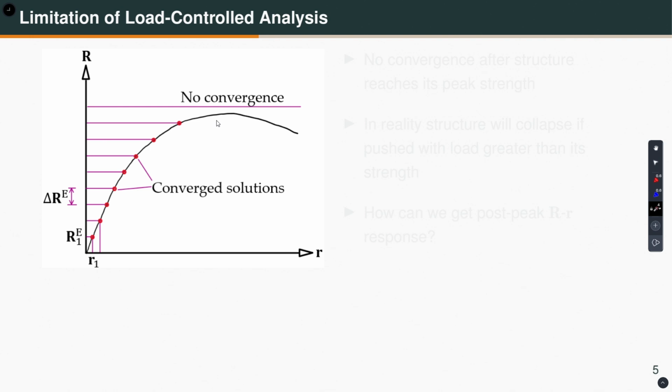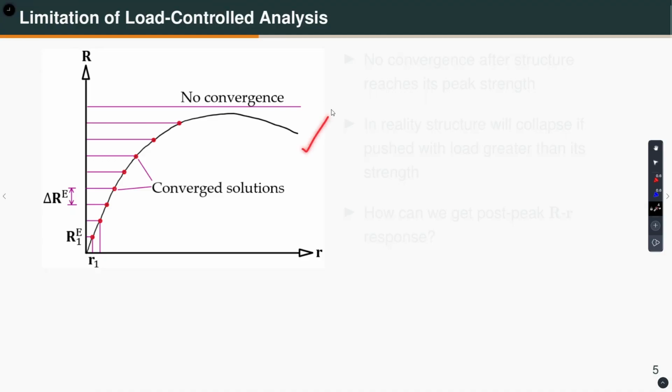Now, in reality, if you do this, reality in the sense, in a laboratory setting, let's say you have a structural component, and typically we use hydraulic actuators, okay, to study the force deformation behavior of structural components and systems. So, let's say you take a hydraulic actuator and you're pushing a component, right, and you are applying load. Okay. So, let us say this component behavior is something like this. So, when you are increasing the load through the actuator up to this point, no problem.